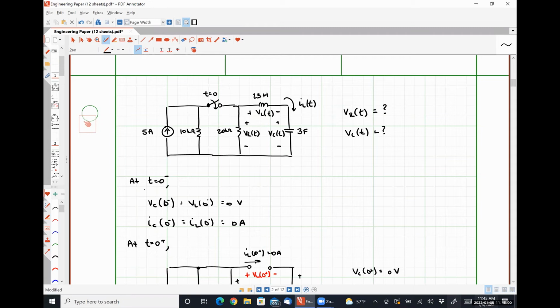The analysis that we're doing here to determine our capacitor voltage, and it would have been effectively the exact same analysis if we were trying to determine our inductor current, involves exploiting the derivative-based relationships and the initial conditions on the system. There is no derivative-based relationship between current and voltage in a resistor, which means we can't use this methodology.